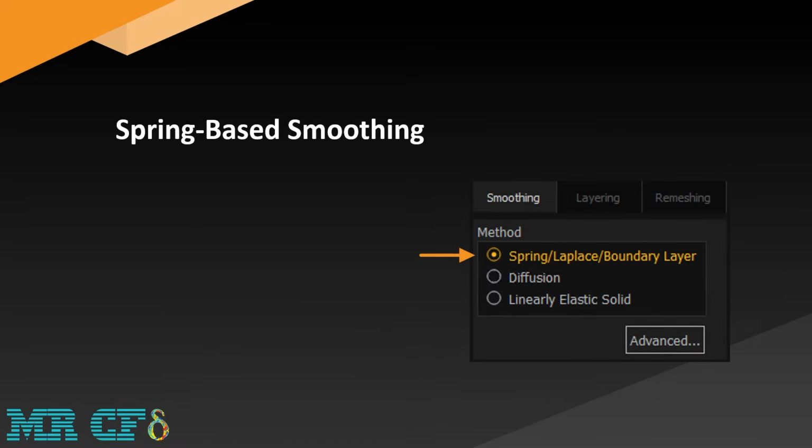In the following, we will introduce the next smoothing methods, known as spring, Laplace, and boundary layer. In the spring smoothing method, the edges between any two mesh nodes are considered as a network of connected springs. The initial spacing of the edges before any boundary movement indicates the equilibrium state of the mesh. A displacement at a given boundary node will produce a force proportional to the displacement along the springs attached to the node.